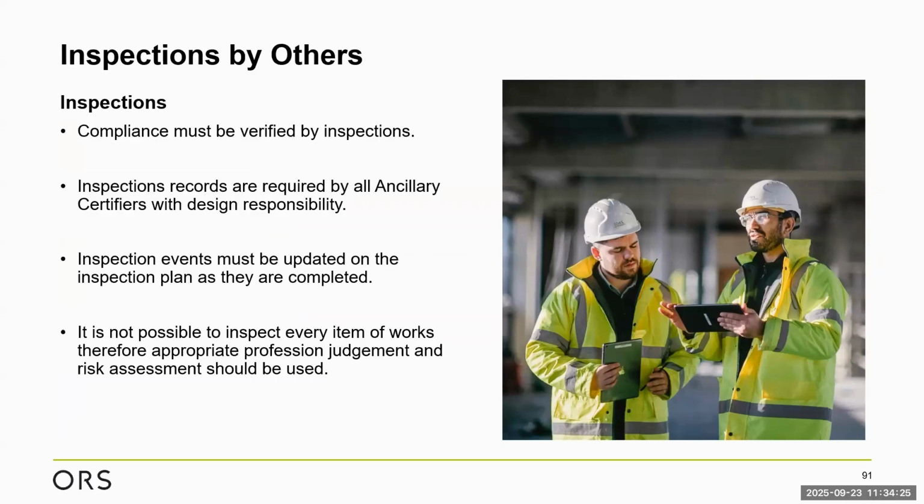Within the suite of auxiliary certificates, we're getting a certificate that attests that the designer has carried out their inspection plan. So, notes here: compliance must be verified by inspections. Inspection records are required from all auxiliary certifiers with design responsibility. And that's kind of my default position: if you design something, you should be inspecting it on site. Inspection events must be updated on the inspection plan as they are completed.